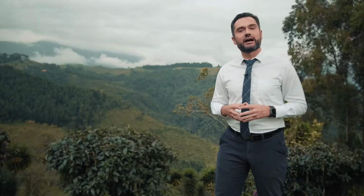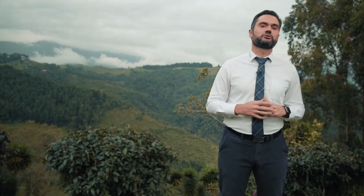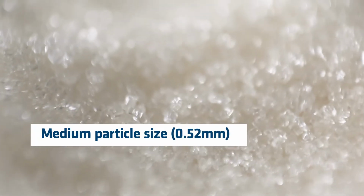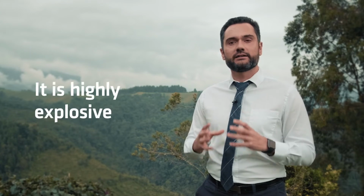Let's take a look at the typical characteristics of the sugar used to produce these products. Sugar is a material with bad air retention. It is very lightweight and has a medium particle size. Its bulk material density is 860 kilograms per cubic meter, and it is highly explosive when handled as bulk material.